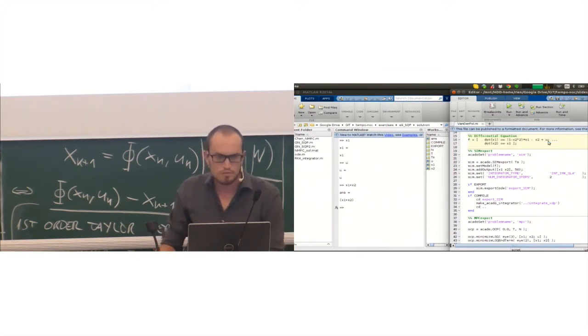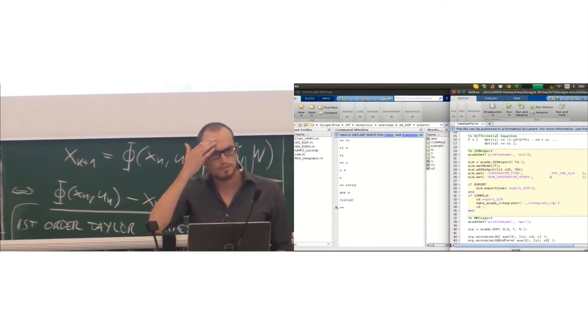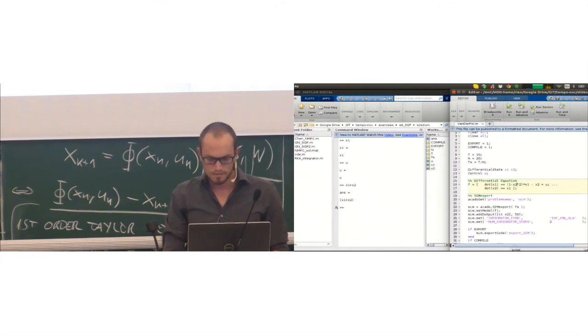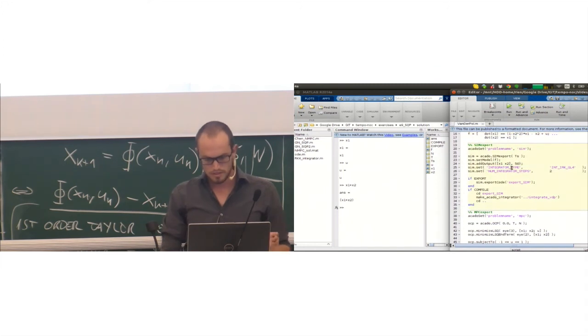I want to do a closed loop simulation, and again, it's going to be this ideal case where my model is the same in the simulation and in the OCP, just for the tutorial's sake of simplicity. So I will also use SimExport, which is an ACADO module that exports an integrator, just simulating your model, similar to the RK4 integrator from the first or second exercise, with very similar, maybe even exactly the same interface, as you will see. I won't explain SimExport too much.